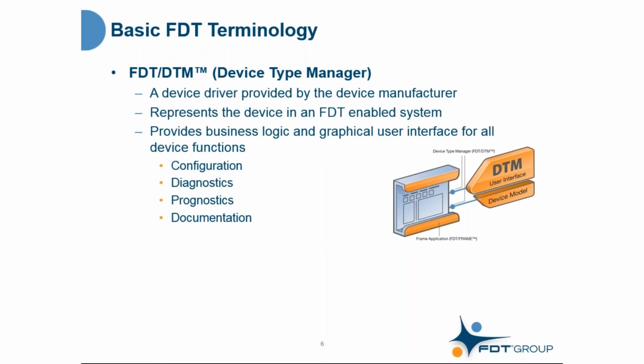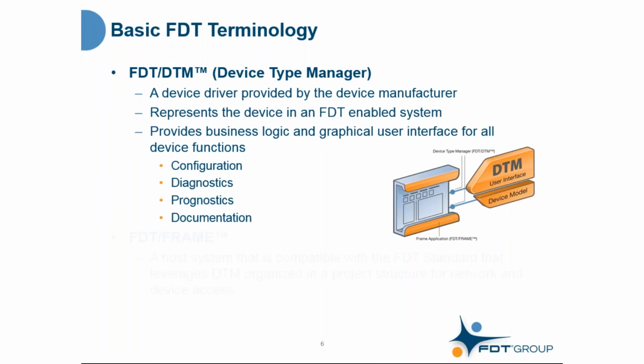This is a device driver that's provided by the device manufacturer, and it represents the device in an FDT system. Inside that DTM is the business logic and a very advanced graphical user interface that supports all the functions of the device, such as configuration, diagnostics, prognostics, and documentation.